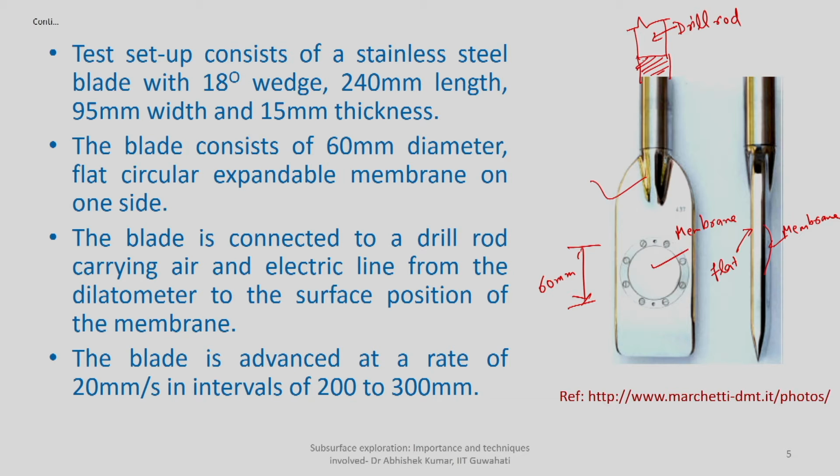As we discussed earlier, drill rods may be 1.5 meter long, because of the pressure we are applying at different depths. So we generally don't go for drill rods of too much length. A drill rod may be 1 to 1.5 meters long. You connect them, and if you are targeting 20 meter depth, accordingly you can count how many drill rods will be required. Very much similar to the CPT test.